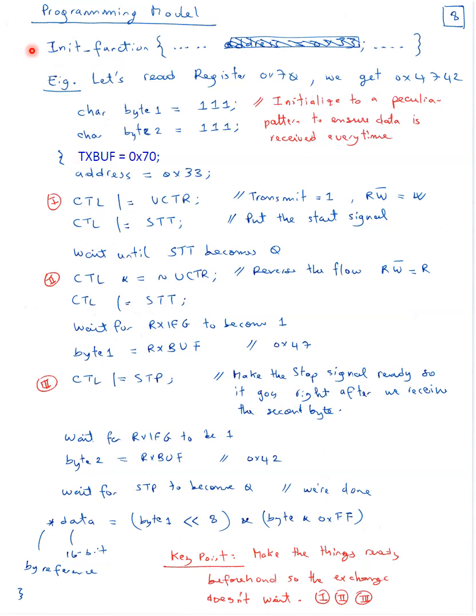I2C is simple to set up the clock. We just do divide. We don't do modulate because the clock doesn't have to be extremely accurate since it is synchronized. So this initialization is a bit easier to write than the UART initialization.